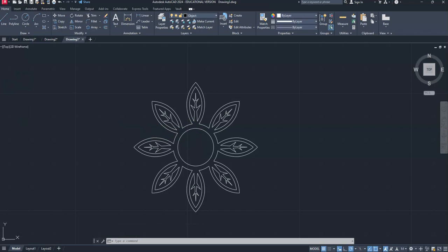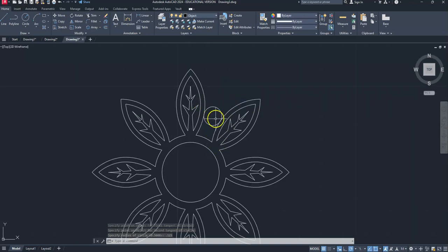Next I'm going to choose my circle, and I want to use a tangent radius, so I could just do TTR if I've already selected my circle tool, and I'm going to say that I want it to be tangent to this line with a radius of 0.125. And that's going to draw in this circle. Now remember, the placement of this is going to be a little bit different depending on the shape of your petal. I'm going to offset this that same 0.0625, and I'm just going to offset my circle.